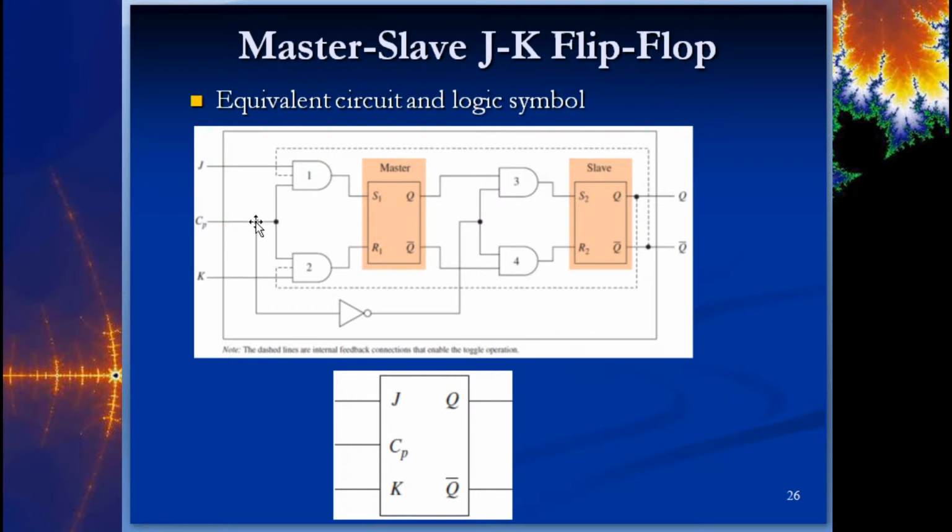And if you have a clock input, a periodic square wave input, what it'll do is it'll take the frequency and halve it, H-A-L-V-E, halve it. So if it's 10K on the input, you're going to get 5K on the output, okay? So essentially the frequency of the output is always half of whatever the clock pulse is, or whatever the source frequency is, okay?